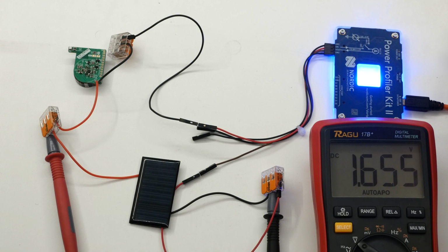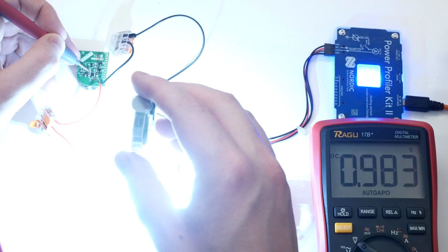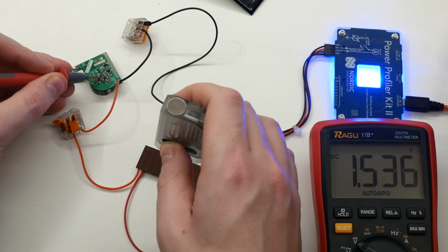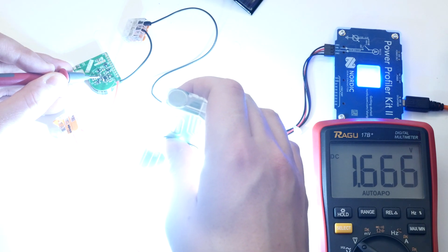I discharged the supercap and moved on with testing the solar panels during different lighting conditions. As you can see, the polycrystalline one does not work in low light conditions, only supplying 2 microamps. But if there is enough light, it is able to fully charge the capacitor. The amorphous solar panels don't work at all because they just don't generate enough energy.